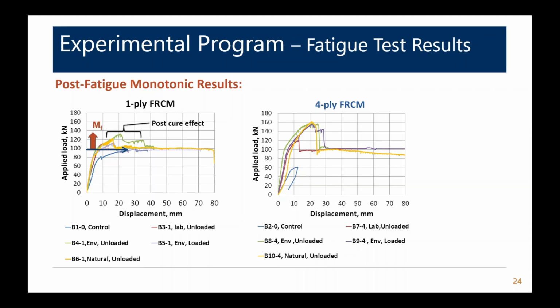But one thing that pops out that's different about cementitious systems is that the exposure to moisture in the environmental chamber actually improved the strength capacity, and it also improved the post-peak behavior. That's the green line. If I had an epoxy-based system, we would usually see a decrease in strength due to deterioration in the resin system. So this is one bonus, I guess you'd say, of a cementitious system.